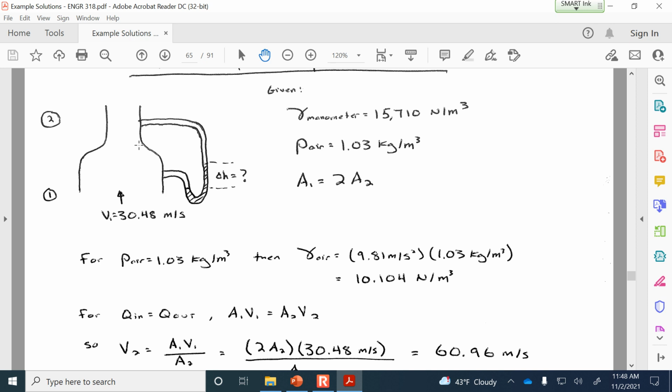change in density. That's one of the assumptions of using Bernoulli's equation, that you have an inviscid fluid that's incompressible. So we're assuming that the pressure is not affecting the change in density between 1 and 2, and it will a little. So anytime we apply Bernoulli's equation, what we observe in the real world isn't going to be perfectly described by that equation, but it's usually good enough that it's worth using.